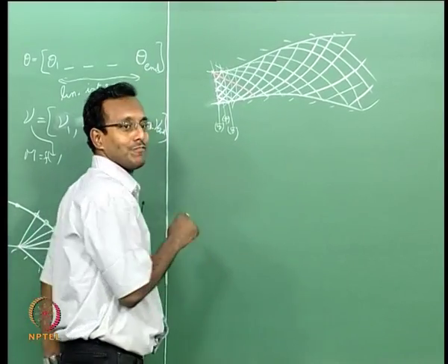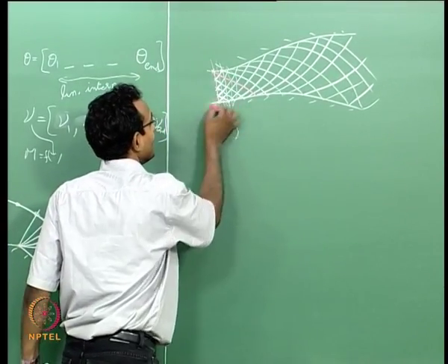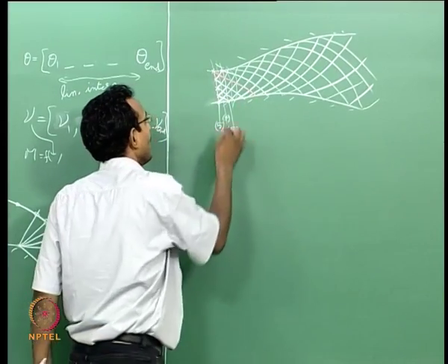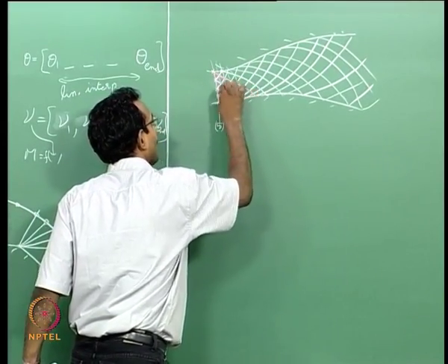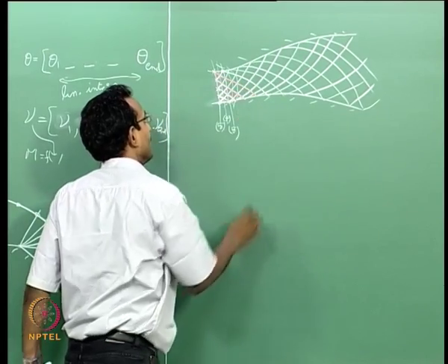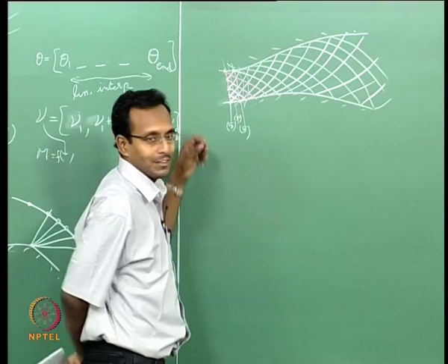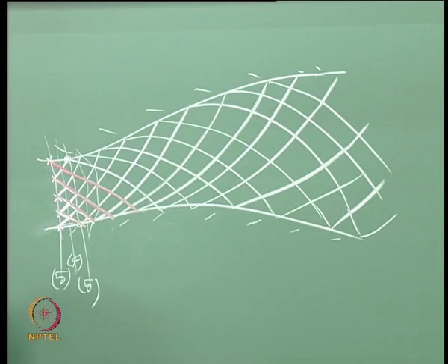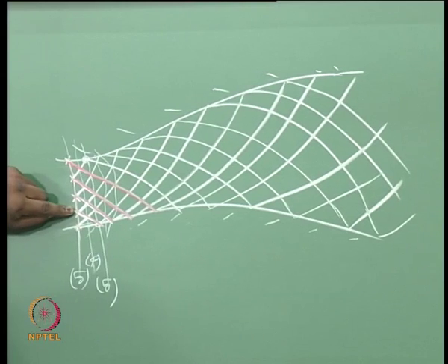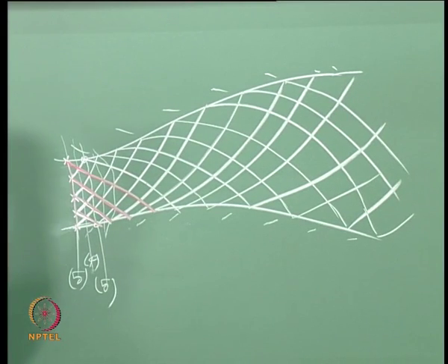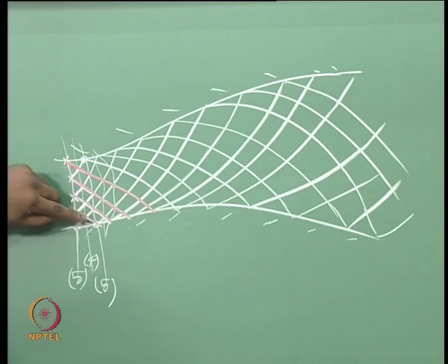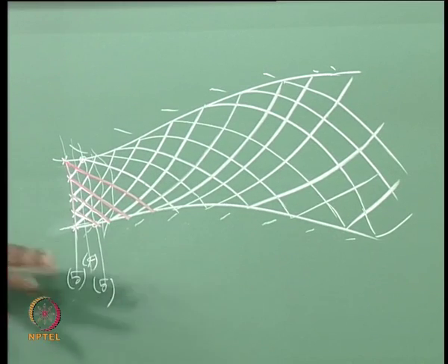What do I mean by fill this triangle? I am going to find all the points inside this triangle and on the boundary. I have found all these points already, which means I am not solving the regular way, starting from one wall going to the other wall. I am solving it differently now. I am going to start from this point, there is nothing to be done. I will go to the next point, from there I will want to go to the bottom wall. I will start a characteristic from there, solving along my right running characteristics, going along the right running characteristic till it meets the wall.